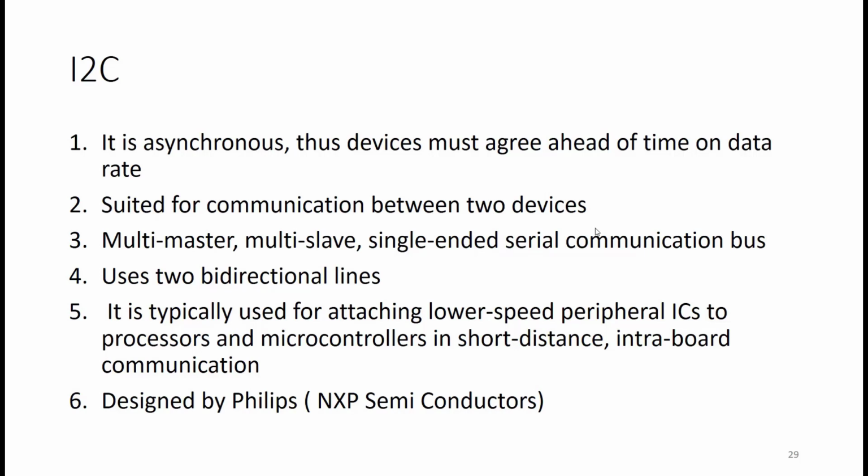To identify the communication of I2C, the best thing to use is a logic analyzer, because there you see the clock signal going along with the data, and when data is transmitted successfully to the slave, it sends an acknowledge or not acknowledge signal to the master.